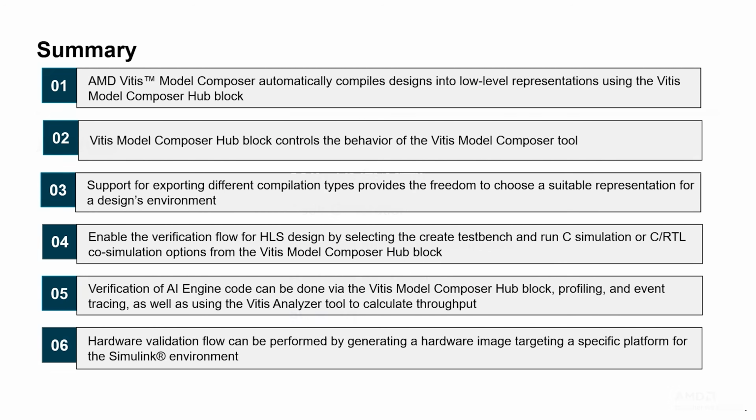In summary, AMD Vitis Model Composer automatically compiles designs into low-level representations using the Vitis Model Composer hub block. The Vitis Model Composer hub block controls the behavior of the Vitis Model Composer tool. Support for exporting different compilation types provides the freedom to choose a suitable representation for a design's environment. Enable the verification flow for HLS design by selecting the Create Test Bench and Run C Simulation or C RTL Co-Simulation options from the Vitis Model Composer hub block.